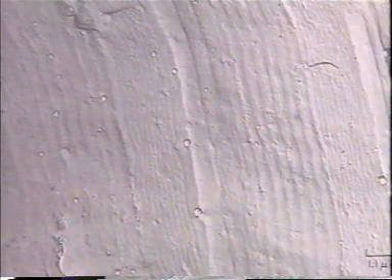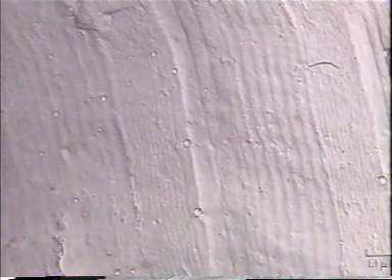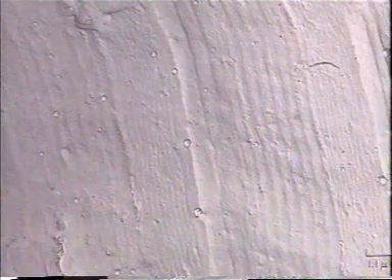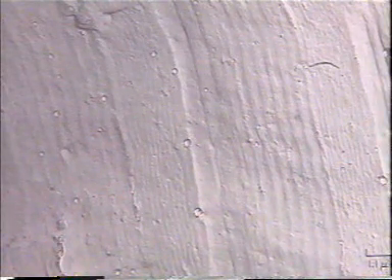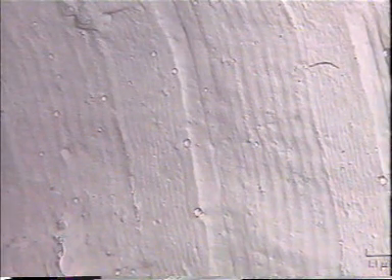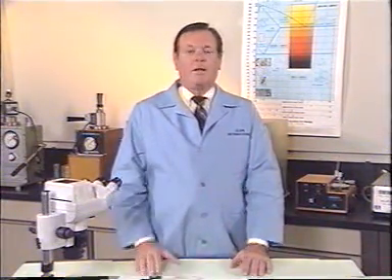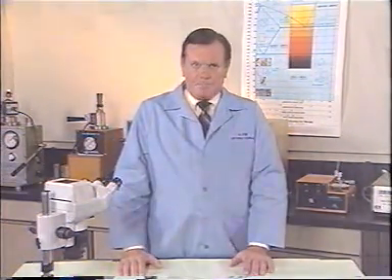They are actually growth marks, analogous to growth rings in trees. These striations are characteristic of fatigue fracture in many metals. However, the striations are not always present, especially when the metal has little ductility. They are also easily damaged by corrosion, mechanical action, or post-fracture damage.